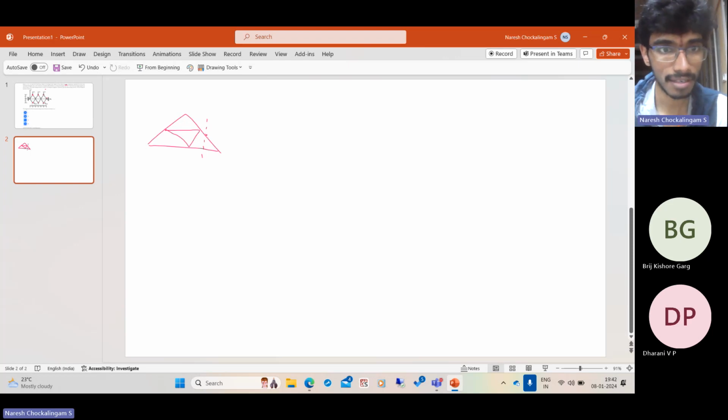So if you have truss members, the direction of the force is known, and it is also known that they don't transmit any bending moments or shear forces. So how the method of sections works is you make a cut, you take one of the resulting bodies and you establish equilibrium on that body. But how many equations of equilibrium do we have for a planar body? We have 3 equations of equilibrium, which means to have some meaningful solution, you have to expose only 3 unknowns.